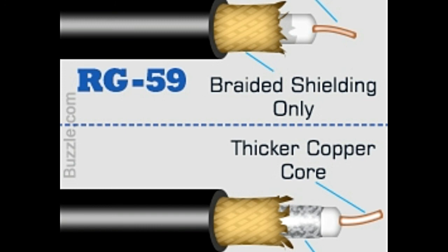Signal loss. RG6 cables generally have better shielding than RG59. This means that signal loss is lesser. Signal loss for RG59 cables at 50, 400, and 1000 MHz per 100 feet is 2.4, 7.0, and 12.0 decibels, respectively. The same for RG6 cables is 1.5, 4.3, and 7.0 decibels.